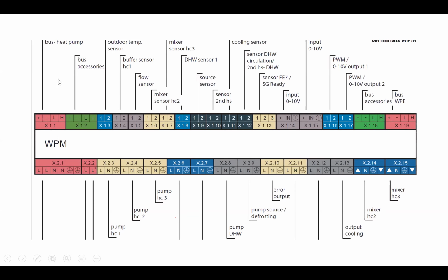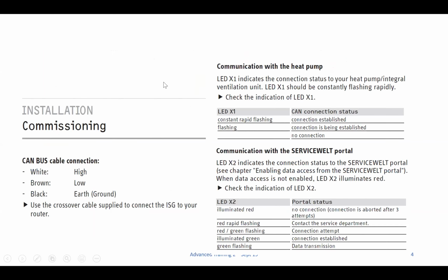And I've, on a number of occasions, said, let me take a photo. Where have you wired your bus wiring into? It's into the red instead of the green. Okay, so be aware, ISG is an accessory. Accessories wire into the green bus network. Okay, ISG. So here is